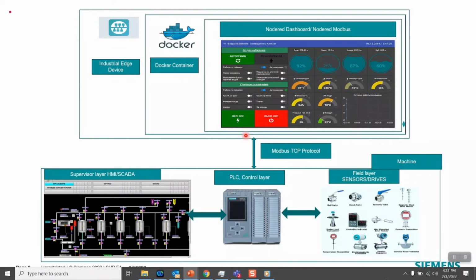We are going to deploy one application which is built in the Linux environment using Python and JavaScript coding, and we have Dockerized that application. After Dockerizing and containerizing that application, we have installed it on the industrial edge device. So we are going to fetch the data from the PLC into the industrial edge device, and one application has been installed over there, which is built on the Linux environment, Dockerized and hosted on the industrial edge device.